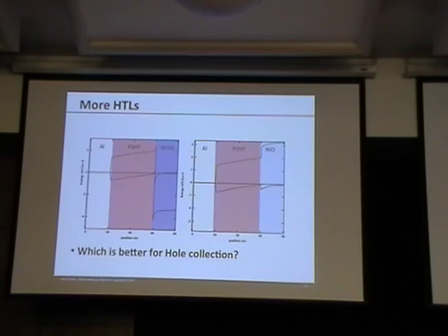Is it happening in the active layer, in what we would normally consider bimolecular recombination, because the carriers aren't getting out? Or is it really happening through some trap states at one of these oxides, at the physical interface between, say, the orbitals of the polymer and the outer electrons of the oxide atoms? Quite honestly, I don't know. I'd love to be able to look at that, but it's not an easy thing.